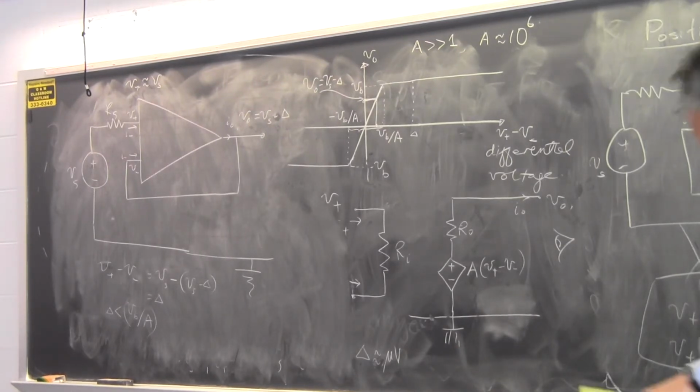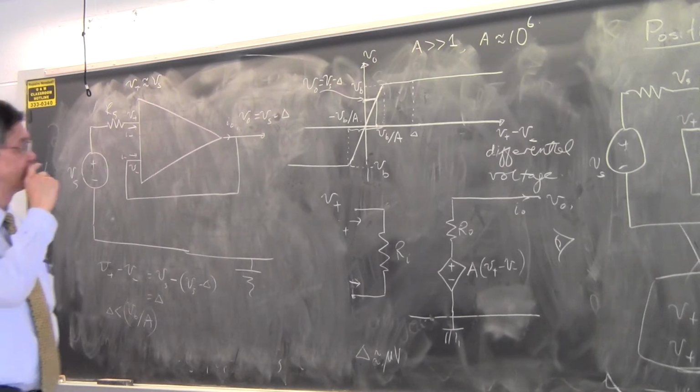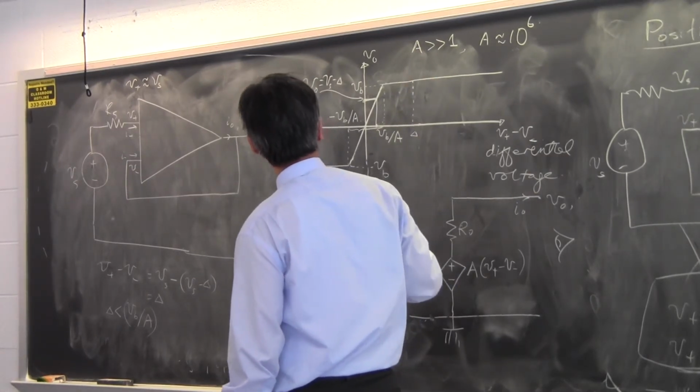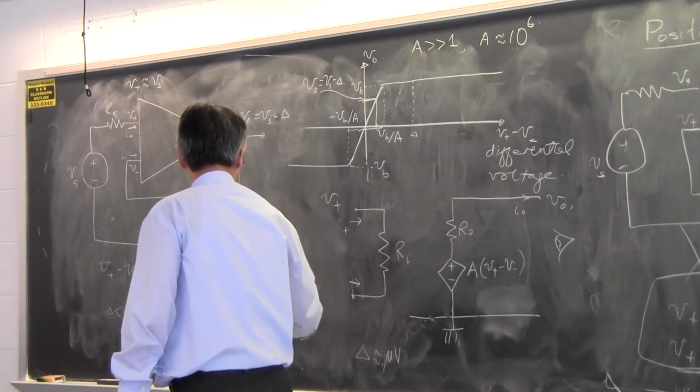Okay. Yeah, there is a way of saying this more succinctly. Let me see how I can say it more succinctly. That if you were to be outside the linear regime, you will give rise to a contradiction over here. So this left-hand picture has to operate in the linear regime. And if you push yourself outside the linear regime, you give rise to a contradiction. Let me see how that goes. So if you were to be outside this linear regime, then VO has to be VB, and let's assume that VB is less than Vs.